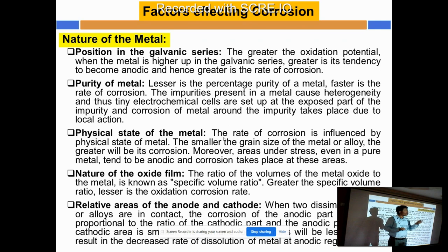So it is highly active if the surface area is more, which happens when it comes to very small, fine sizes, because fine sizes have more surface area. So smaller grain size leads to high activity, because high dissolution means high activity. More active means more oxidation, so more corrosion. So the physical state is also very important. Understood now the third point, physical state.